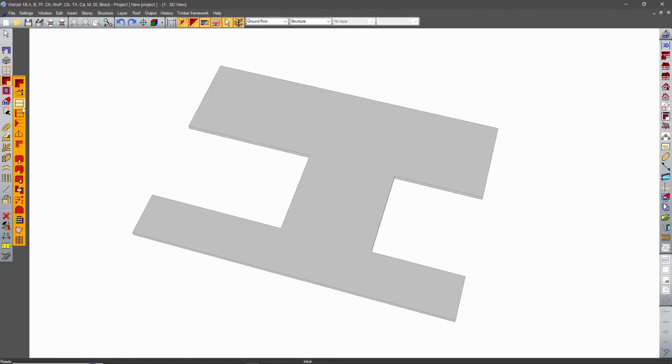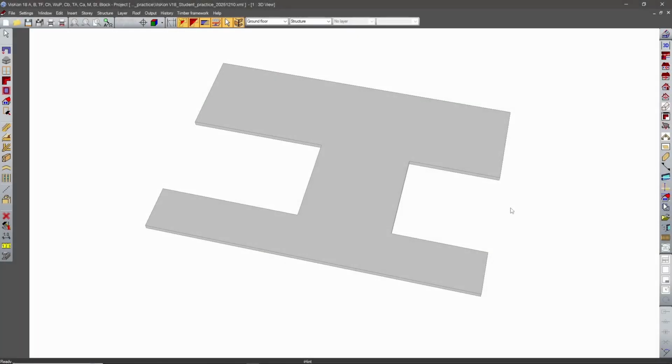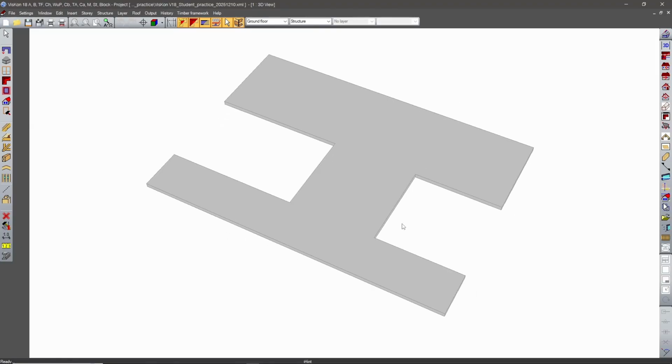We use dual pitches wherever we can, and the other side's gonna be completed with single pitches or gables. In this specific case, in the middle portion, we're gonna use the T-gable. Now the T-gable comes really handy when you want to create a smaller gable roof perpendicular to a bigger one. Let's create the pitches, and you will understand even better.